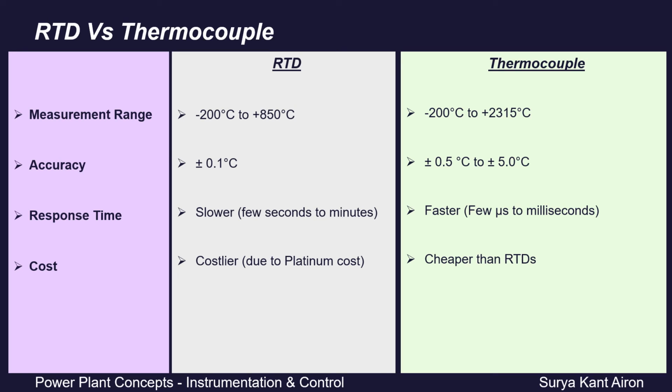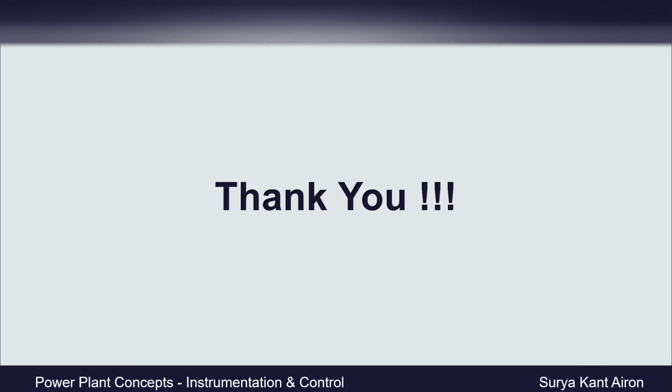So friends, to summarize, for an instrument selection out of the thermocouple and RTD, first we have to look at the process temperature range which we have to measure. Then we have to make a judgment based on the accuracy requirement and the budget. If we need higher accuracy, then we use RTDs, and if we need a cost-effective solution where slightly lesser accuracy can be accommodated, then we should go with thermocouples. So friends, I hope now we are clear where to use an RTD and where to use a thermocouple for our requirement. Hope I am able to clear the concept well.